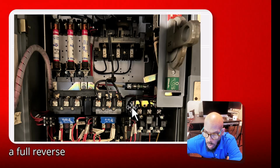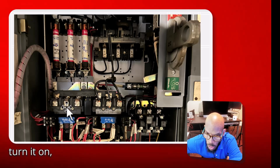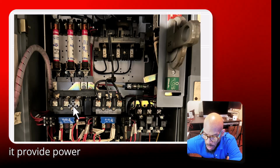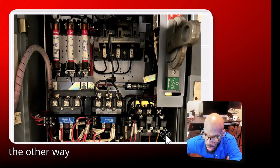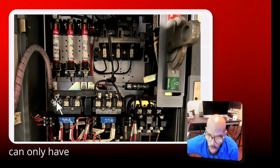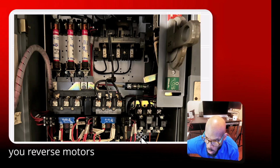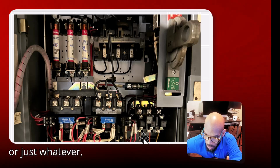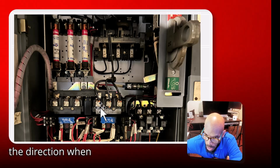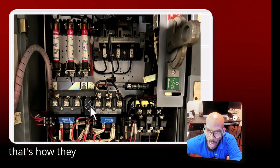So this is a forward reverse starter because it's got 2 of these on here. When you turn it on one way, it provides power going one way, and then when you turn this one on, it provides power going the other way. Now these are interlocked, so you can only have one set of 3 on at a time. And that's how you reverse motor direction, or the pins, or whatever. If you reverse the direction on a 3-phase circuit, then you're just switching some of the wires. So that's how they do it.